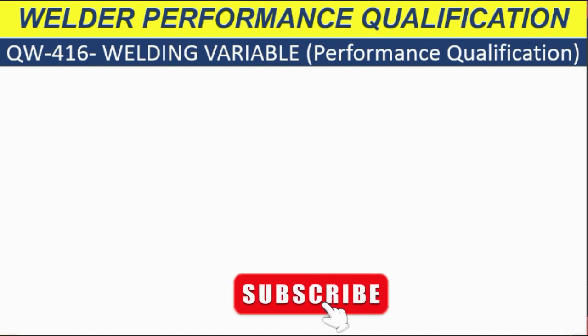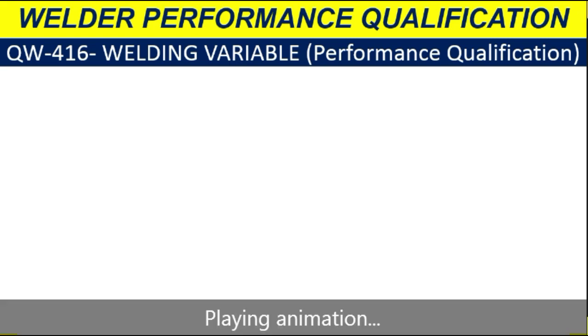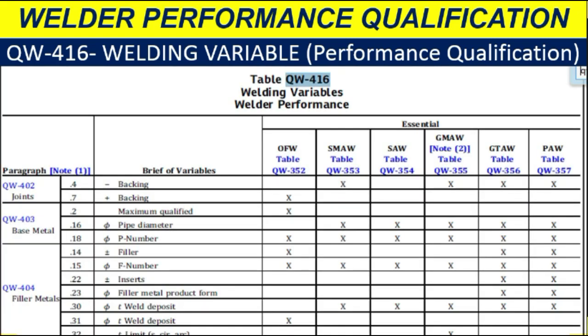You see here QW416, that is the welding variable table for performance qualification. You have to understand that QW416 is one chart given for all processes. You see here OFW, SMAW, SAW, GMAW, GTAW and PAW. All these processes have their essential variables given here. Now I will not go through the full chart. You can go directly to ASME Section 9 QW416 and get the details.